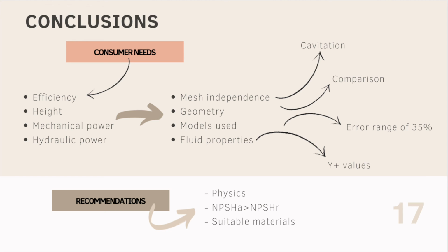In the mesh, the recommended values of Y+ were fulfilled since the simulated fluids showed values below 5, which allowed a good approximation of the model. It is important to highlight that the Y+ must always be below 5 or above 30, since in the buffer region the curve doesn't give a good fit of the system. For this reason, it is known as a transition region and it isn't recommended to place any cells in this zone.